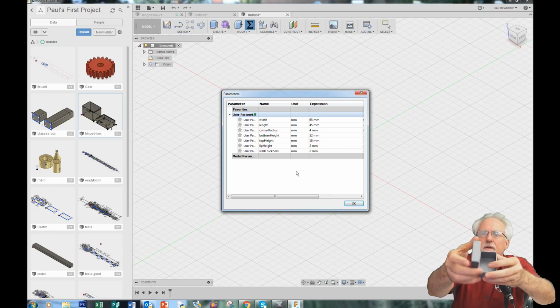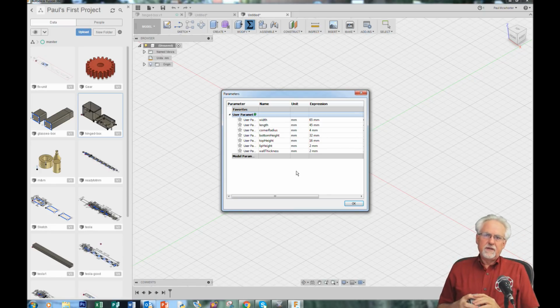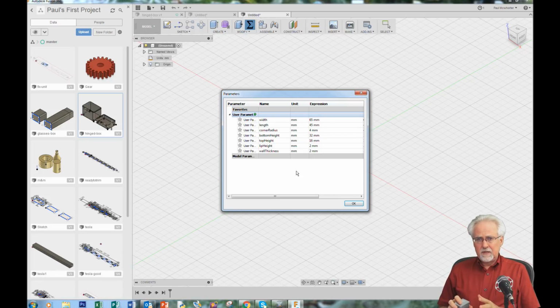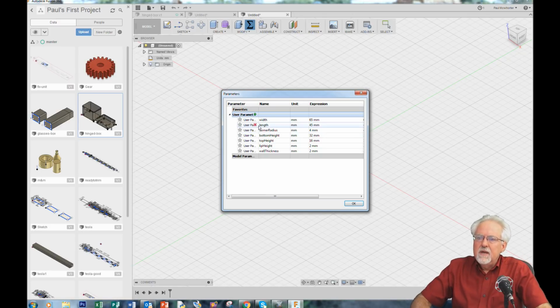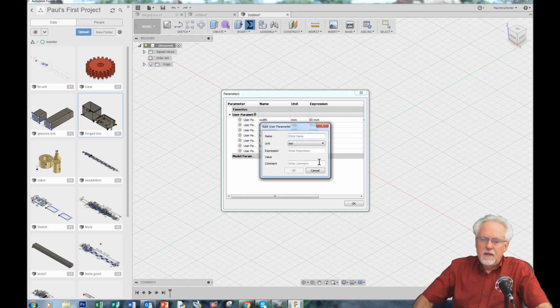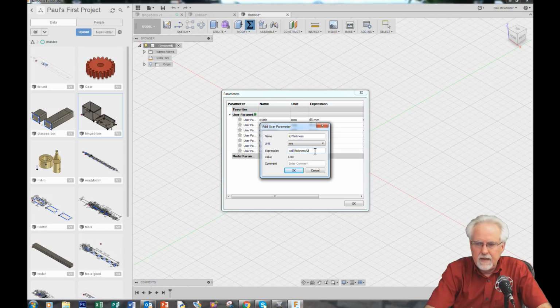And then if I have a wall thickness, what else do I need? I need a lip thickness. Now, is lip thickness a dependent variable or an independent variable? Can you just go pick out any lip thickness you want? No. Lip thickness is related to wall thickness. The lip should be half of what the wall is. So it is a new parameter, and I will call it lip thickness. All right. But it is going to be equal to wall thickness divided by 2.